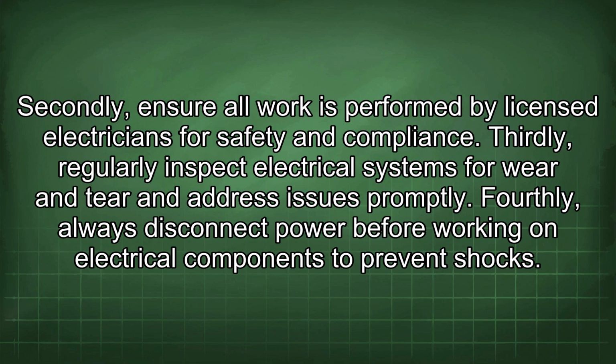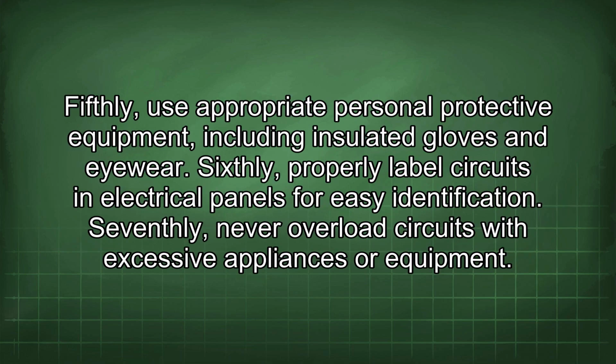Fourthly, always disconnect power before working on electrical components to prevent shocks. Fifthly, use appropriate personal protective equipment, including insulated gloves and eyewear. Sixthly, properly label circuits and electrical panels for easy identification.